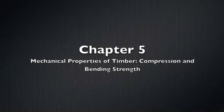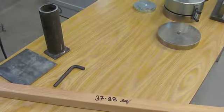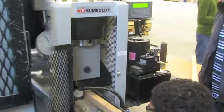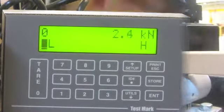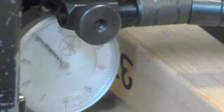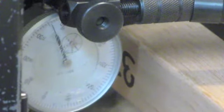Today is Laboratory 5, Mechanical Properties of Timber. We're going to start with bending strength. For this, you're going to need to know the depth and width of a beam, as well as the distance of the clear span in between its supports. You're going to load this beam up in flexural bending and record the deflection every quarter of a kilonewton applied.